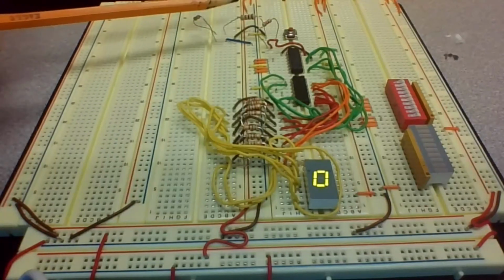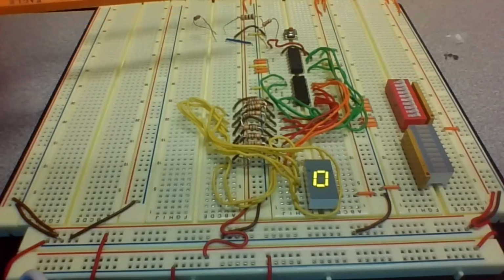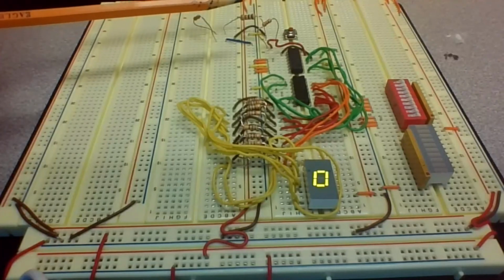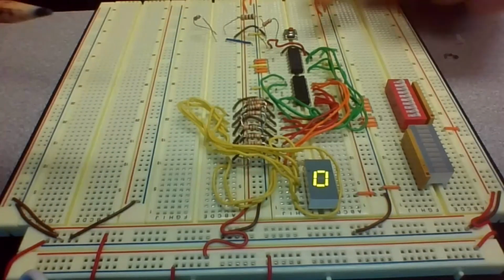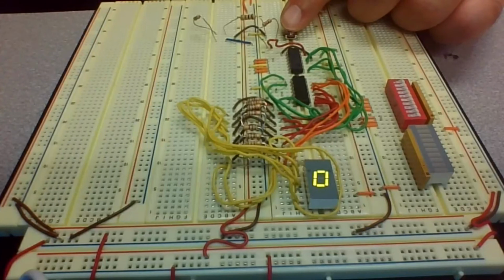Here we use one small resistor circuit, which somewhat fixes the problem, but it sometimes still happens even with this circuit. Okay, so let us start counting by pushing this switch. We are on the 0, I push the switch, I release, and it actually gets 1 and 2, which means because of the bouncing switch, it actually got 2 pulses.